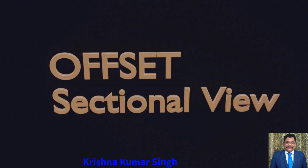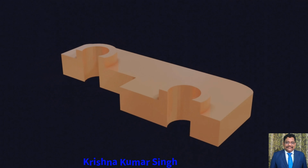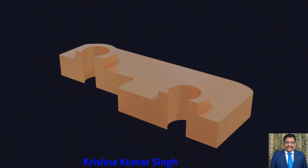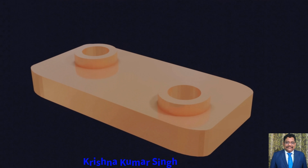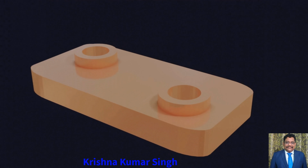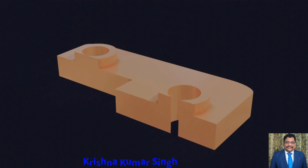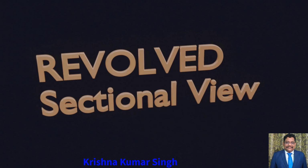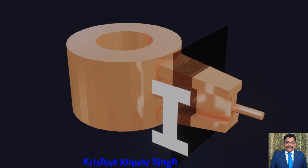Offset sectional view: when the configuration of an object that needs to be highlighted is not located on a straight line, then an irregular cutting plane is imagined which sections the object to give the desired view. The view obtained is an offset view. Revolved section view: this view shows the shape of an object by rotating a part of the object by 90 degrees. The view obtained in this section is a revolved view.